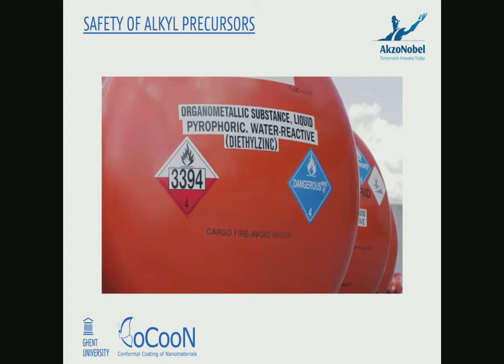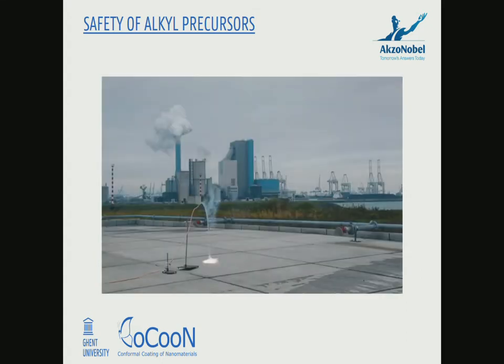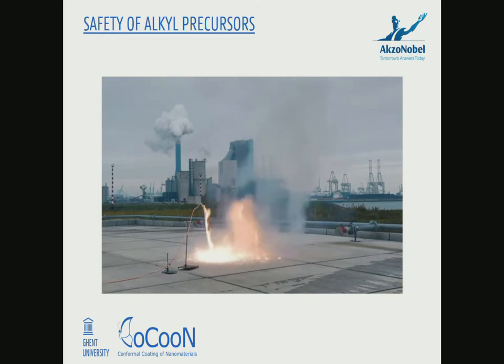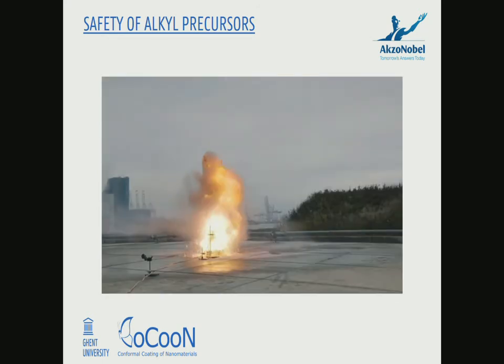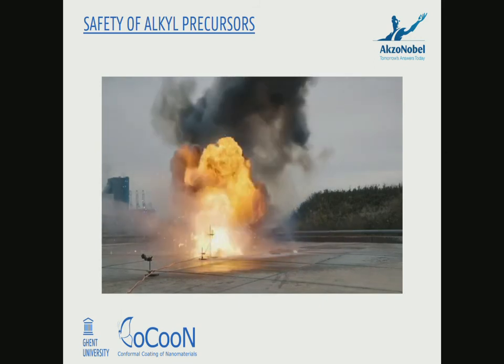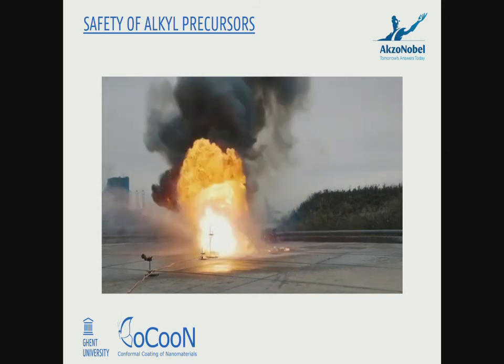Since many of you will be working with diethyl zinc and trimethyl aluminum, there's one thing from a safety point of view that I would like to briefly highlight. Some of these precursors are highly reactive. They have to be highly reactive because they have to very efficiently react with these OH groups of your surface. The fact that they are highly reactive means that some of them are also pyrophoric. This here is a movie from AkzoNobel. This is diethyl zinc that's just being exposed to air. And this is what happens if you try to extinguish the fire with water.